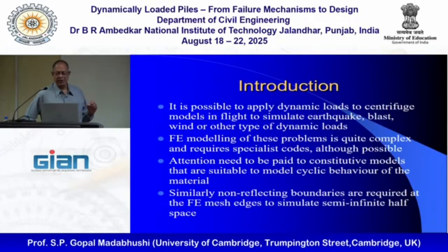But the most important thing is really the constitutive models that are available. When you're doing dynamic problems, the constitutive model should be able to handle this type of cyclic behavior of the material. Especially for soils, we talked about yesterday that the soil is non-linear and also plastic. It also has this other unfortunate habit of trying to change volume.